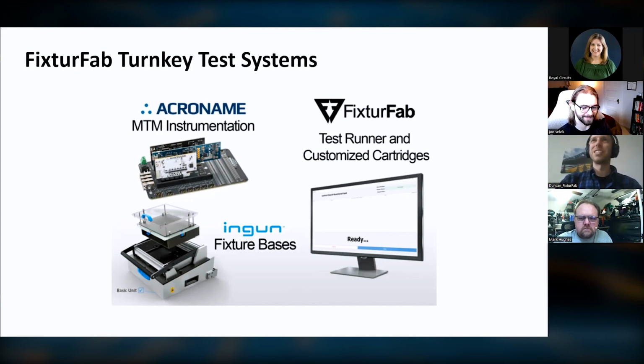It depends on safety, like where it's being manufactured and exactly what you need. But we do have features that we can integrate into the fixture bases to allow for high voltages. We've done a couple of fixtures with high pot testing, where we're high pot testing modules inside of these things. In that case, there are safety interlocks to make sure that the fixture can't be opened when high voltages are present inside. For line voltages, it's pretty simple as well.